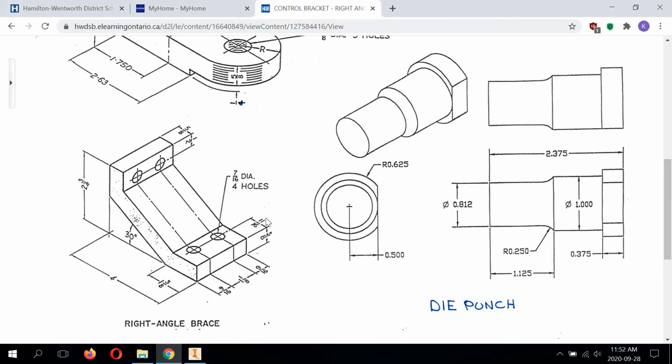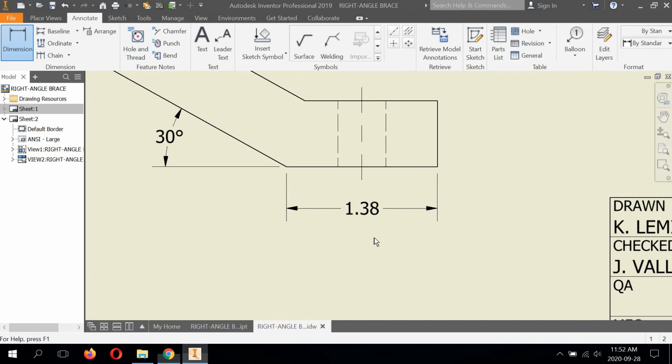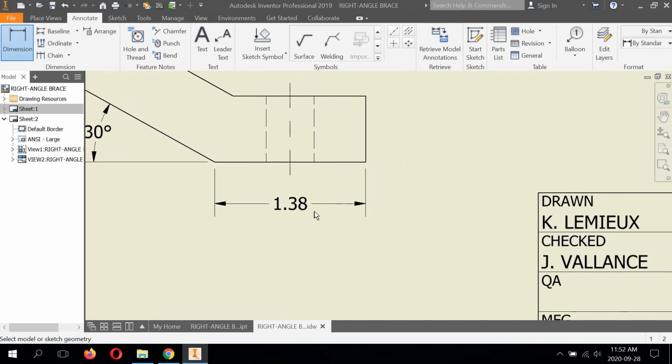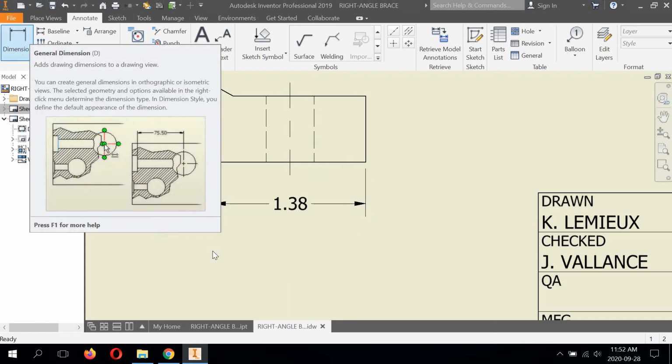Right? I'm breaking my rules here and I'm clicking back and forth. All these dimensions are meant to be shown as fractional, but this is defaulting to decimal form. So we need to change this. We're going to change this once and apply it to the rest of the dimensions. So we can right click, left click OK. That's going to escape us or end the dimension command.